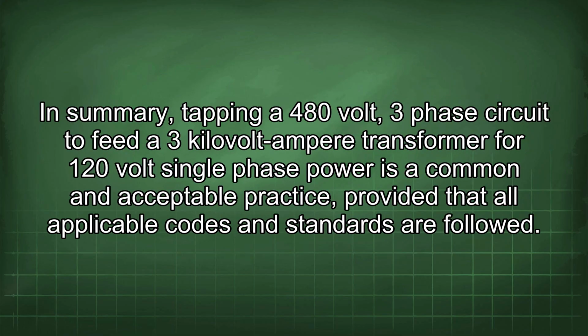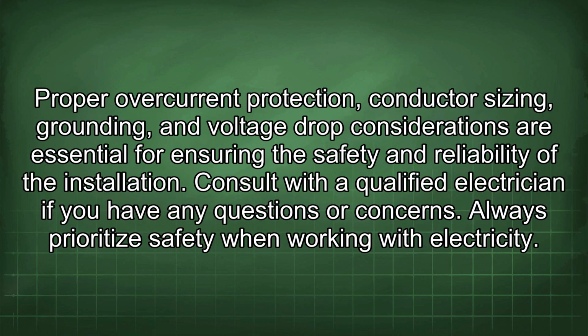In summary, tapping a 480-volt, three-phase circuit to feed a 3 kilovolt-ampere transformer for 120-volt single-phase power is a common and acceptable practice, provided that all applicable codes and standards are followed. Proper overcurrent protection, conductor sizing, grounding, and voltage drop considerations are essential for ensuring the safety and reliability of the installation. Consult with a qualified electrician if you have any questions or concerns.